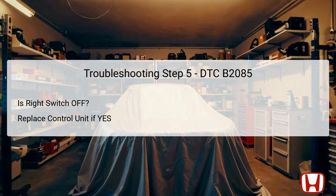If the HDS indicates that the data for the right power slide door half-latch switch is off, this is a strong indication that the issue lies within the control unit itself. In this case, the appropriate action would be to replace the right power sliding door control unit.